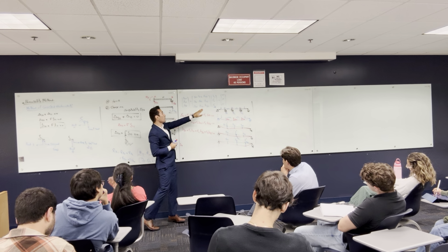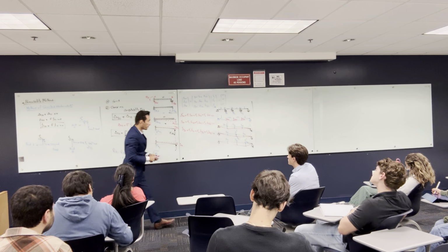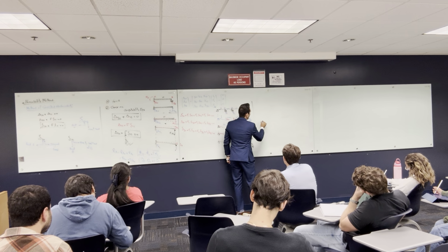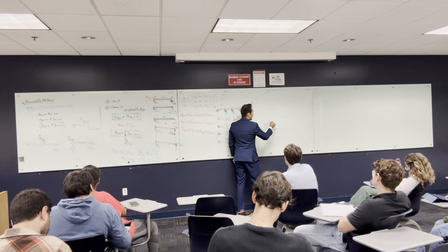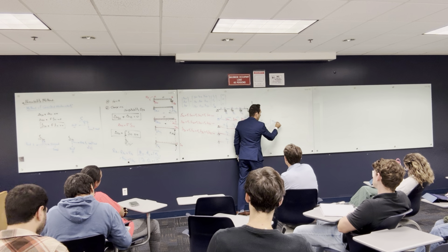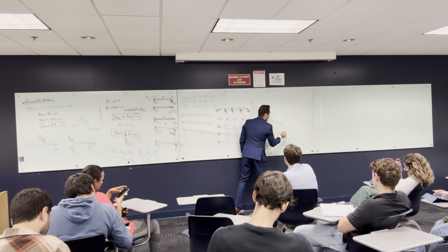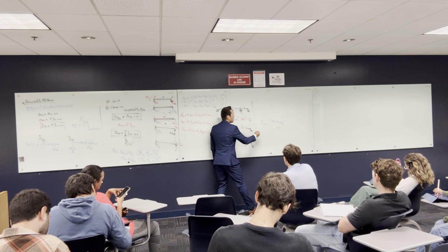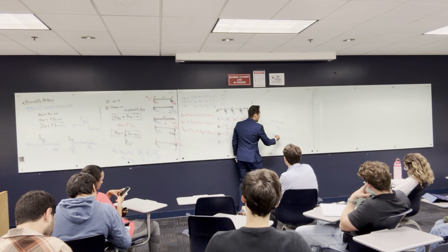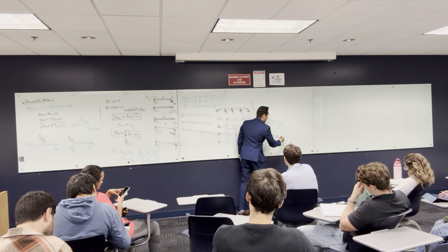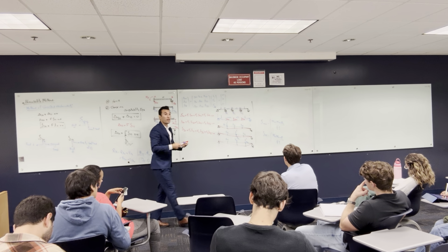Okay? So this is called the deformation matrix. The way to find the deltas, like any delta, delta MN, is going to be the integration of the moment of M multiplied by the moment of N, dl over EI. So for example, if we want to find delta 1O, we have to integrate the moment from the original system plus the moment that comes from 1, dl over EI. So that's how we learn in virtual work.